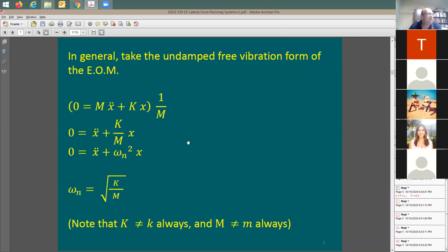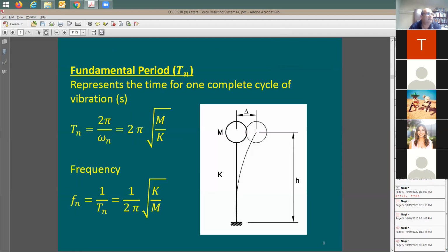We have our natural frequency. Our natural period is going to be really what we care about. So this natural period is going to be very important for us to work with buildings. A building for me is going to be a single degree of freedom system. It's going to be a mass, stiffness, and damping is going to be 5%. You don't have control over this when it comes to code design and analysis.